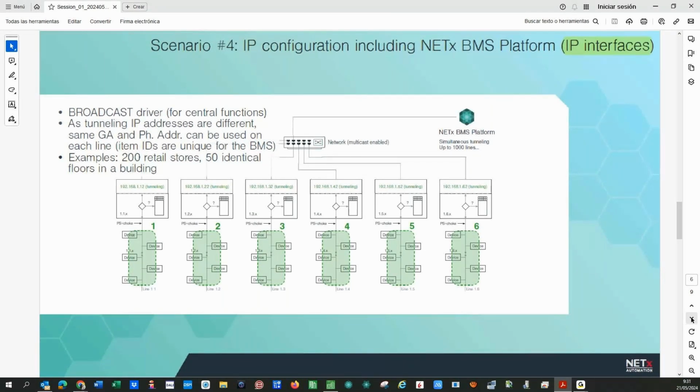And this is also adding security for your project, because it's impossible that from one room you can control different rooms as an end user. So if an end user plugs into the KNX TP line of his room and tries to sniff the traffic of the telegrams, as many integrators can do, and tries to turn off the lights of the neighbors and whatever, it's not possible because they are isolated.